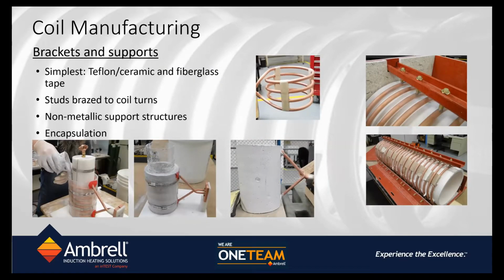Once the coil is made, you have to determine what kind of environment it is going to be in. Does the coil need to be encapsulated in ceramics? Does it need to have support mechanisms on the side, like studs as shown in the top right picture here, to hold the turns in place? Because if we've spent all this time and effort designing a coil with variable turn spacings, you want to seal in those turn spacings. So an easy way to seal in the turn spacing is by encapsulating the coil.